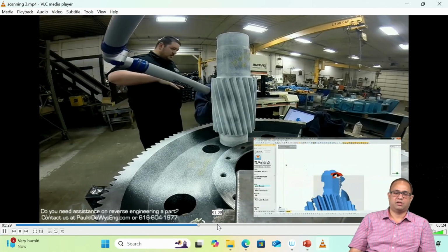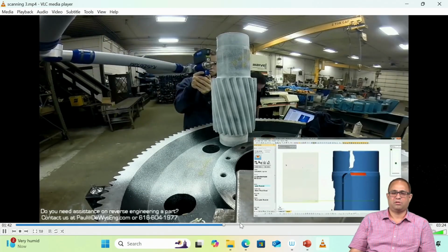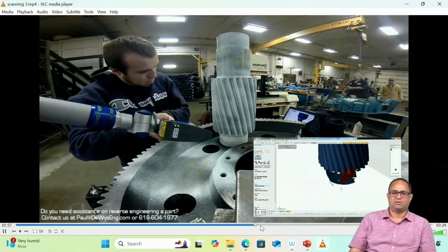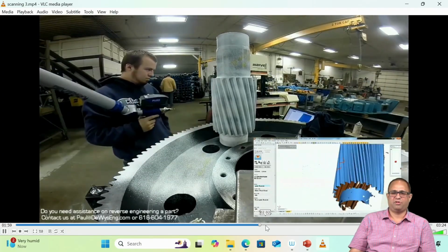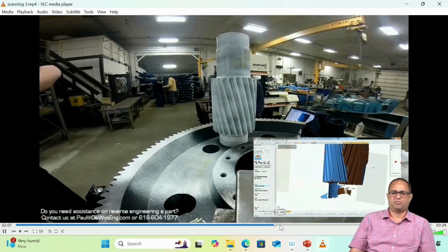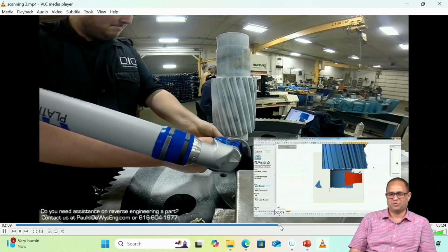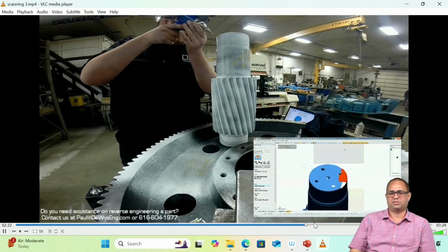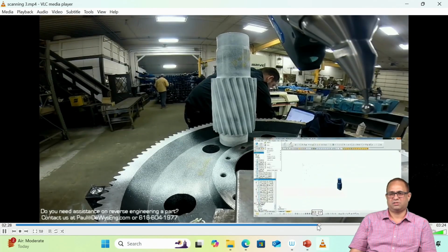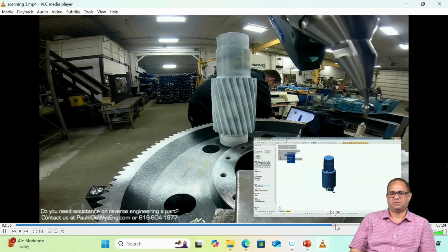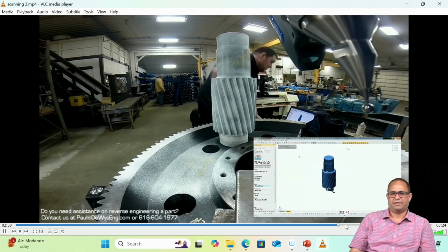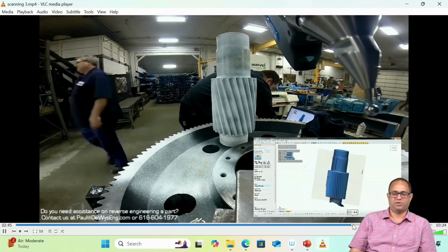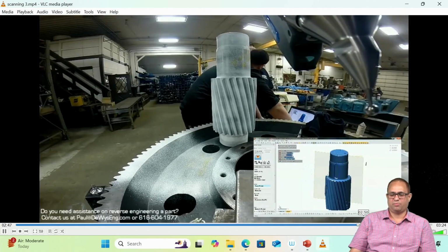And then the same thing, there's a processing of point cloud, as you can see here. See how each and every feature is going to be scanned. This requires precise experience also, where to start and where to end, etc. And how to avoid the noise factors, as you can see here. And whatever scan area is missed, again we need to work on the area which is already missed here.